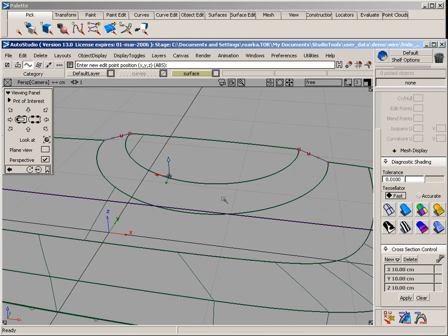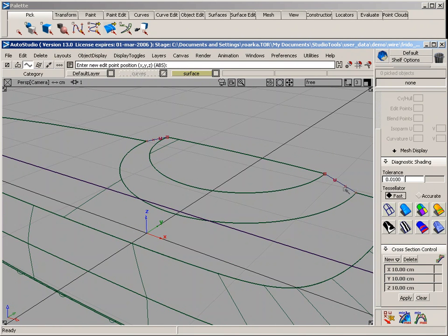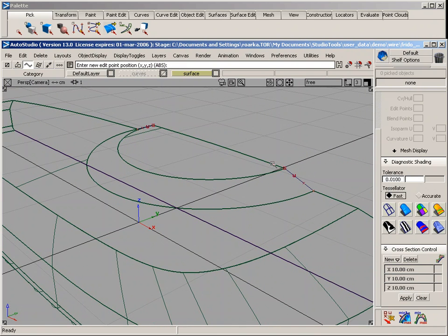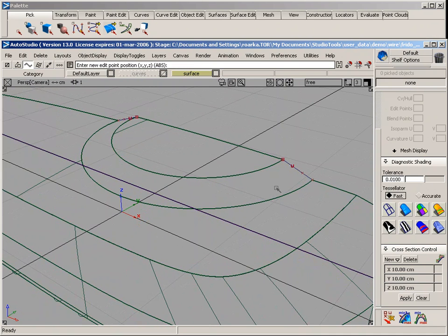If I'm going to rail this surface now, I will get a very clean chisel or bevel look. However, for this particular exercise or demonstration, I want to create a surface that hopefully will appear very tangent and integrated into the main body. So it's a very soft transition. For that, I have basically 2 options. I could rail this surface and use the round tool on both sides here to create a small round or fillet. Could also use the surface fillet tool. However, I'm going to try to create a surface that is tangent to begin with.